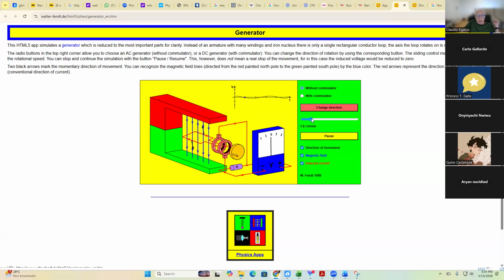Watch this. Let's increase the rotation so you can increase the voltage. We can hardly see anything here. Here you go. Now you can see the voltage is oscillating back and forth. A minimum value right in here, pass through zero, maximum value, minimum value. Let's see if I can pause exactly at zero. Exactly at zero is where the magnetic flux is maximum. Okay, and so on. Let's write that down.